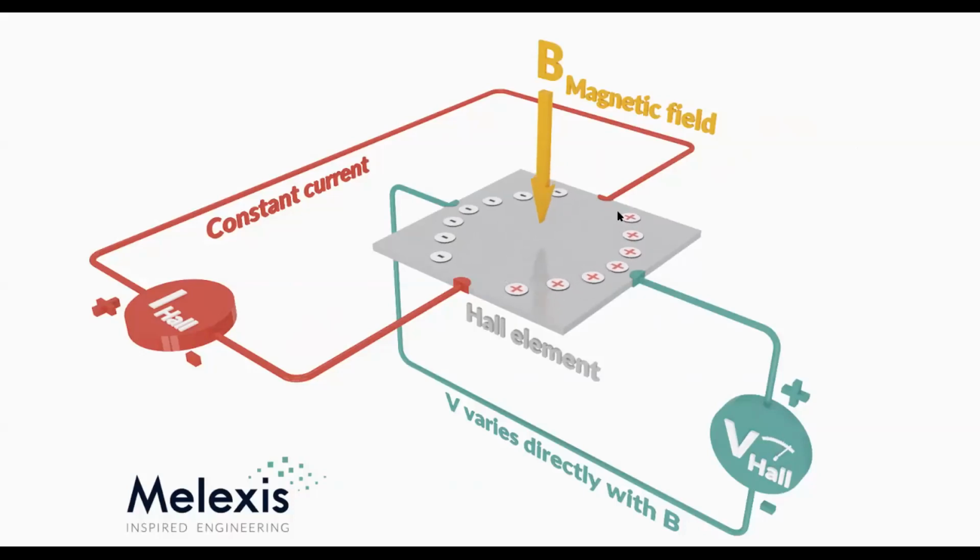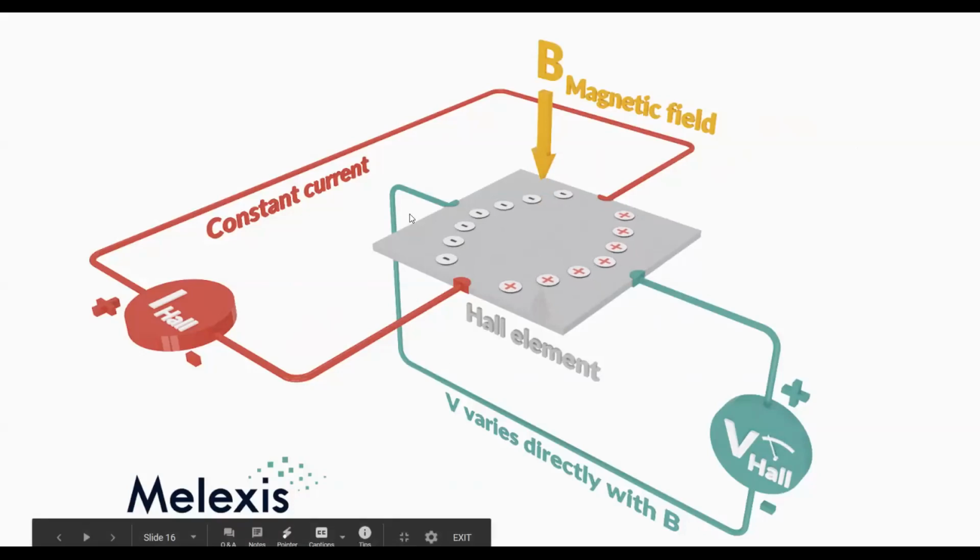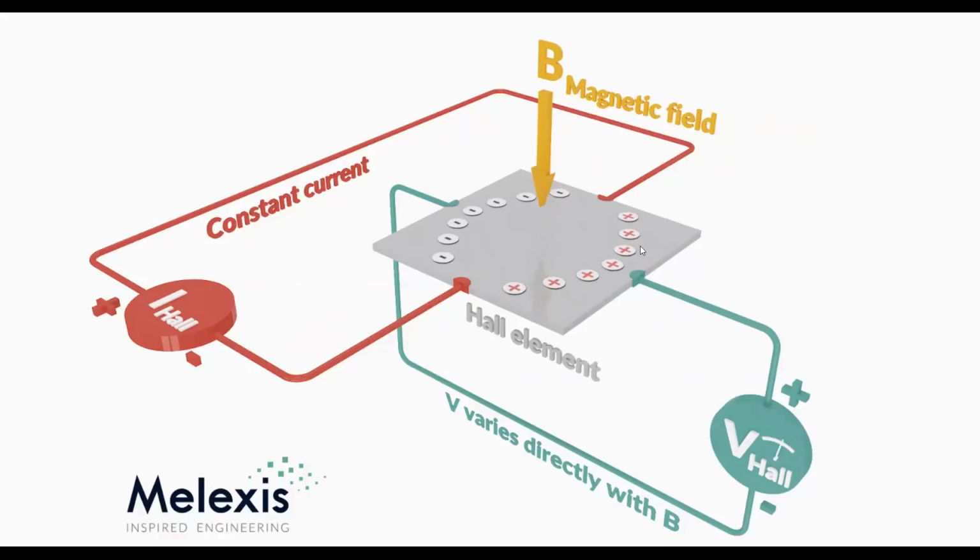And at this point, there will be a voltage that you can measure across the two terminals of this conductor. So there's a lot of current sensors that are based on this effect. The reason that we're not using this is because it's generally less accurate than using a shunt resistor, and the measurements can be impacted by magnetic fields that aren't part of the high voltage current path. So any kind of interference that the car would be exposed to will also change the measurements for the current.